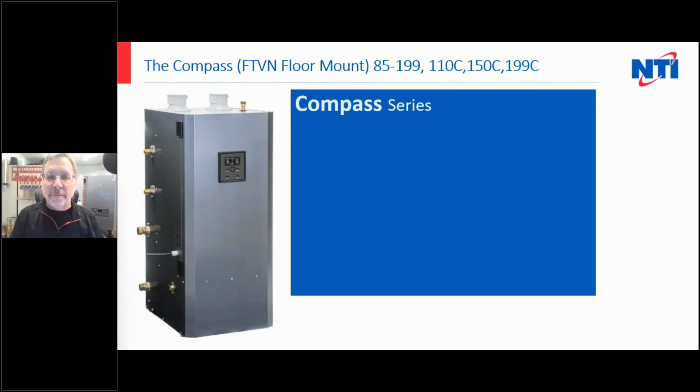If you're going to do that, fire tubes are a phenomenal thing. If you're not going to do that, consider doing water tubes and cleaning the combustion chamber every year on propane, every 2 years on natural.